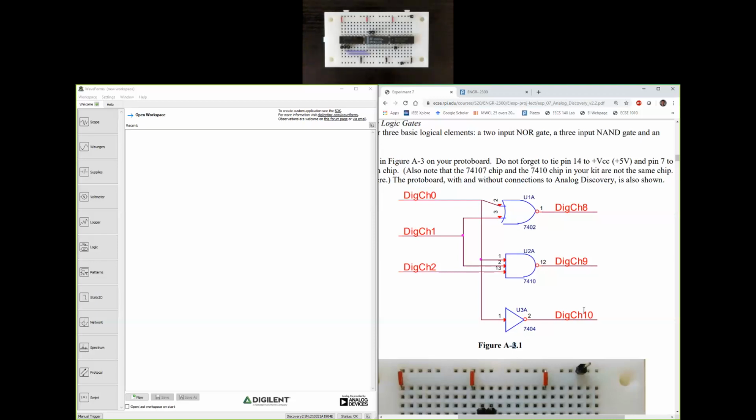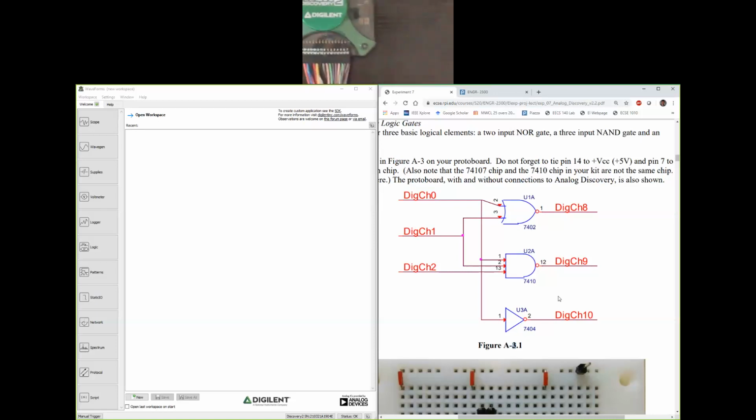The Analog Discovery gives us 16 digital I/O. You can take a look at that on the digital I/O of the Analog Discovery. If you look at all the connections on the right here, we have not been using them. The purple and the brown and the pink, all those connections starting from 0 through 7, 8 through 15, all those 16 pins, those are your digital I/O.